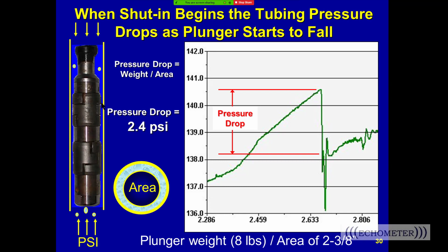If your packer is set very high above the formation, that's like setting your C nipple high, and it causes the cycle to not be steady. The liquid will collect below the hole in the tubing to the top of the formation and slug in the tubing and kill your cycle. So you typically have to operate at much higher casing pressures and much lower load factors if you have a packer with a hole shot through the tubing to use the casing. It's a lot easier without a packer. Conventional plunger lift, it's a lot easier without a packer. So that's my comments about a packer.